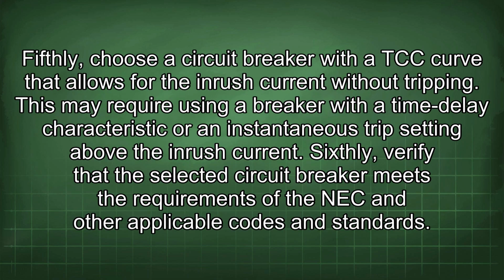Fifthly, choose a circuit breaker with a TCC curve that allows for the inrush current without tripping. This may require using a breaker with a time delay characteristic or an instantaneous trip setting above the inrush current. Sixthly, verify that the selected circuit breaker meets the requirements of the NEC and other applicable codes and standards.